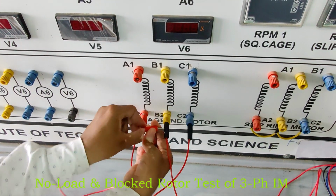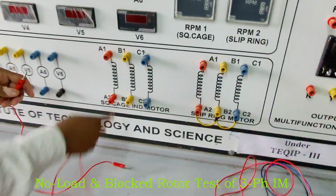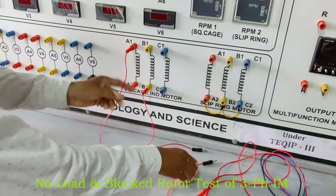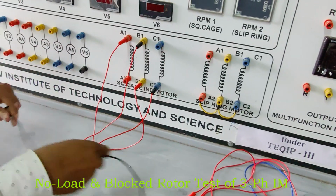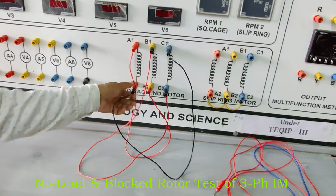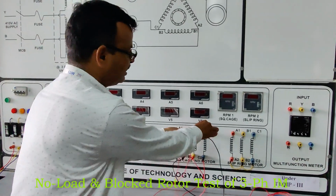Neutral points. Now suppose you have to connect in delta. Delta is nothing, just to avoid the terminal. The delta connection is like this: A1, B1, B1, C2, and C1, A2. This is the delta connection. In the delta connection, there is no neutral point. So you may connect in star or delta, but in this experiment we are considering the star connection.